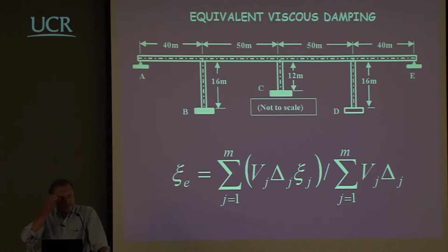On the opposite, it is clearly easy to define the property of each one of these systems, and if you think in terms of displacement-based design, the parameter that you will use for each one of these systems, and then you combine to have something which is equivalent to the force reduction factor in a force-based approach, is essentially the equivalent damping.